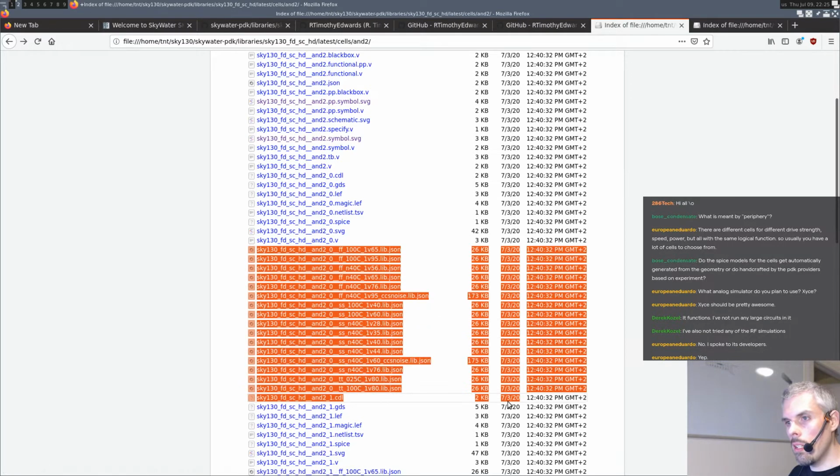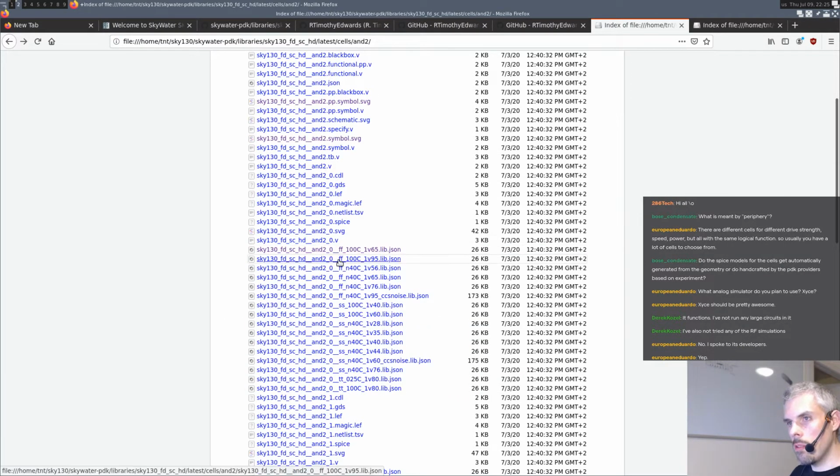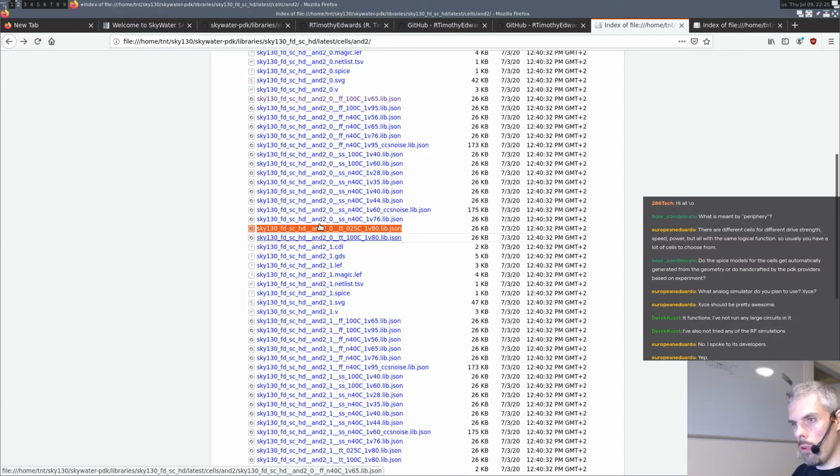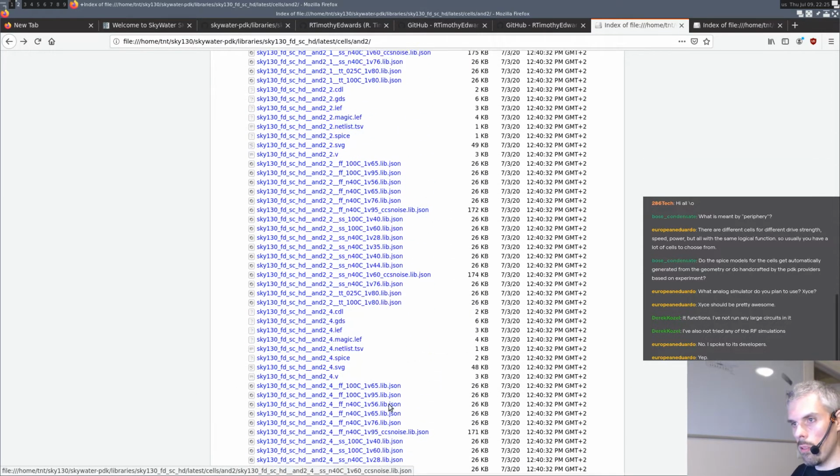And so they provide the timing data also for different operating points. You see, you have the fast process corner, which is like the best case, at negative 40C and different voltage and stuff like that. And then they also provide, thankfully, typical performance data. That's for every cell you'll find.